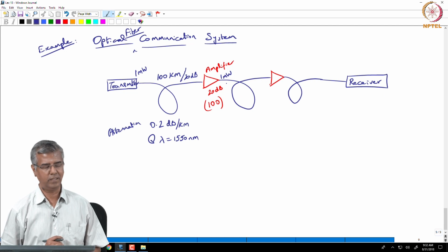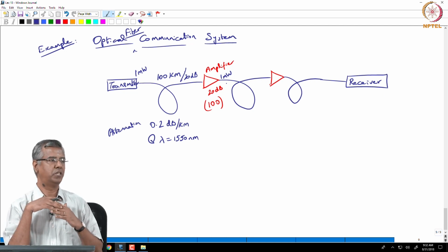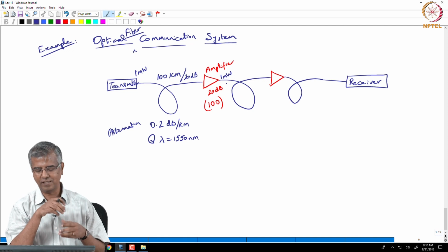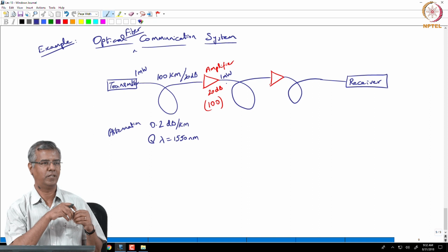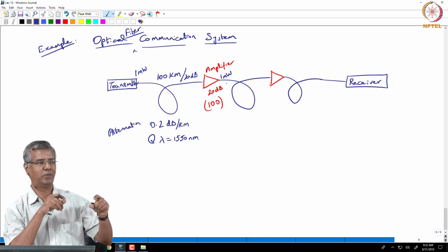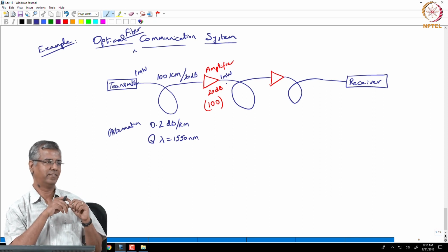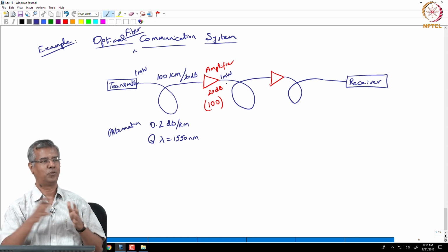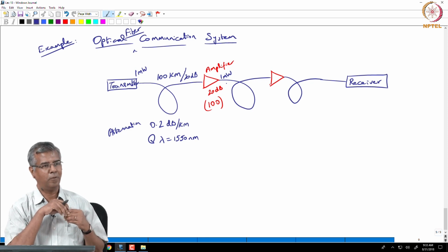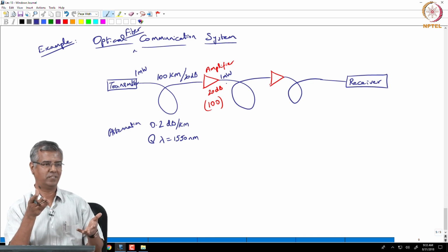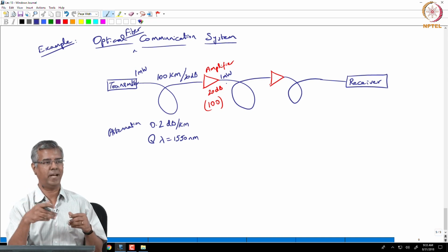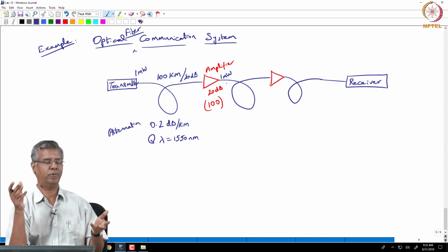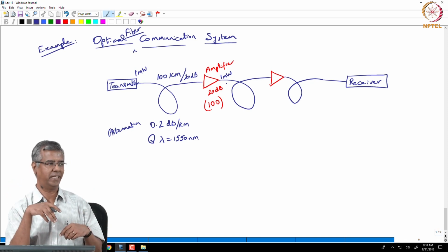So, your overall signal to noise ratio keeps reducing, and this is not just optical amplifiers, even other electronic amplifiers. You will see that before you get to do that amplification is the highest signal to noise ratio that you have. You say, okay, but through an amplifier you are amplifying the signal, but you are also amplifying the noise, whatever noise was present at the input, and that amplifier adds its own noise. So, the net effect is the signal to noise ratio is only going to degrade.